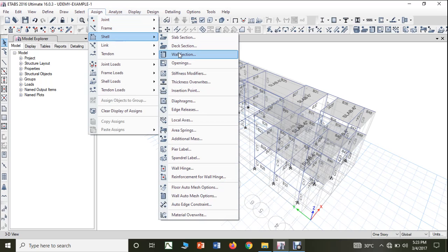The next is the wall section. Similarly, if we have defined any wall, then the corresponding wall can be assigned here after drawing it. Here, whatever walls are present, we have converted that wall loading to a UDL and applied it on the beam. Therefore we have not taken the wall section, and we have not considered walls here. Otherwise, similar to the slab, whatever wall sections we have defined and drawn would be assigned.